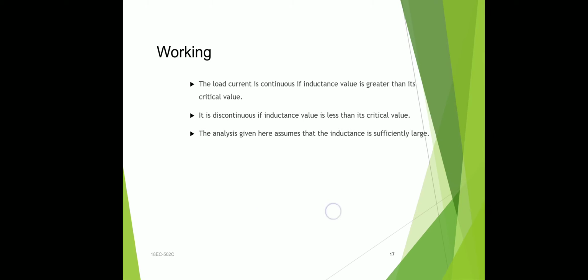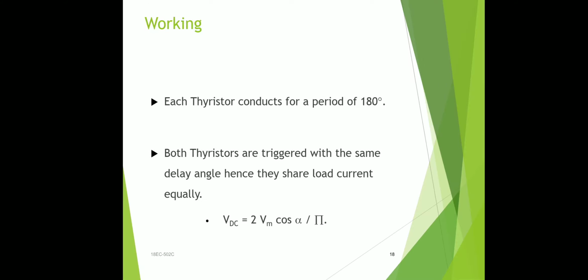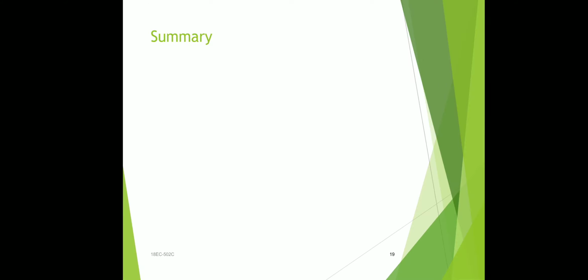In this session I discussed 2 circuits. The main topic is single phase fully controlled rectifiers. What is a rectifier? It converts AC to DC. Fully controlled means the full cycle is completely converted into DC form. In controlled rectifiers, the output value can be controlled, by varying the firing angle. By changing the firing angle, the output voltage can be varied.